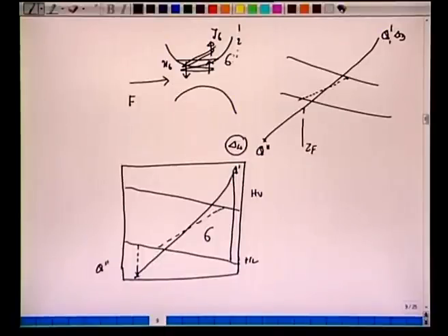The feed is in between the 6th stage here and the next stage, if we continue from here, then this would be your 7th, if we leave room for this feed entry. Okay, or maybe this is the 7th stage. So the feed enters between the 6th and the 7th. All right. So once we reach this, now instead of connecting to this Q dash, we are in the stripping section. Now we have to connect to this. Of course, this line can be a solid line, extended to obtain the second stage.